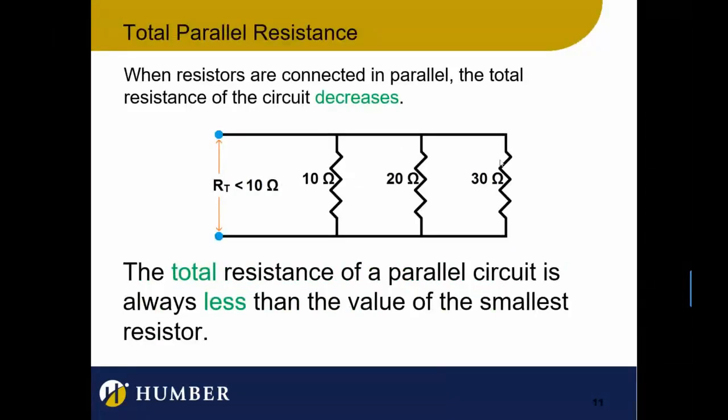So now the total parallel resistance. I'm just going to stop here for a second, guys, before I move on. What we just found out was that in a parallel circuit, the current is divided, kind of like how in a series circuit the voltage is divided, but it's backwards. In a parallel circuit, the voltage is shared. Everybody's got the same voltage, and the current's divided. In a series circuit, everybody had the same current, but the voltage was divided. So they're kind of inverse, and we'll see that. You've learned series circuits; that's kind of your foundation. We jump into parallel circuits, everything's backwards, and we'll see that the total resistance is also totally backwards, and it's so cool.